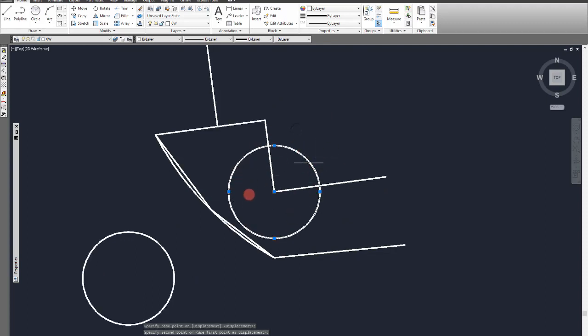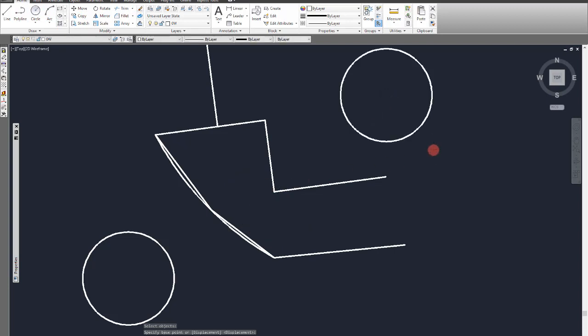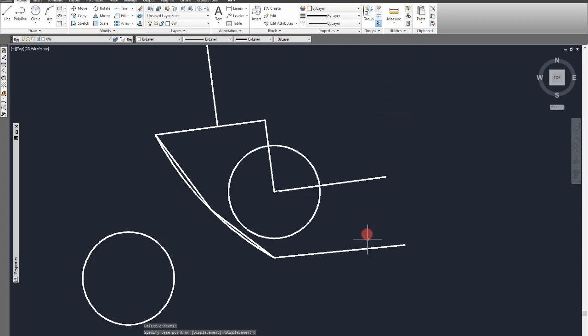Of course, you can type the command. The command is easily typed by pressing just M if you wish not to go to here, and select the circle and move it. Again, M, select the circle and move it. The shortcuts for all these commands I used are very simple. Usually they're the first letter of the words or the first two letters if the first letter is used for another command. For line, it is, you guessed it, L. You type L.